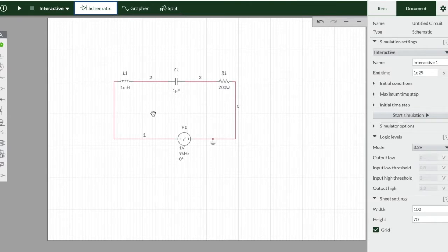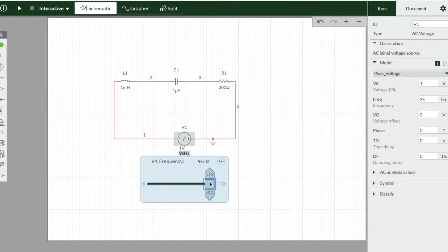We are first going to verify whether this circuit shows resonance at the input signal frequency equal to 5035 Hz as per the theoretical value. For this, initially we will select the frequency to be much smaller. Let's start with a frequency of say 300 Hz.